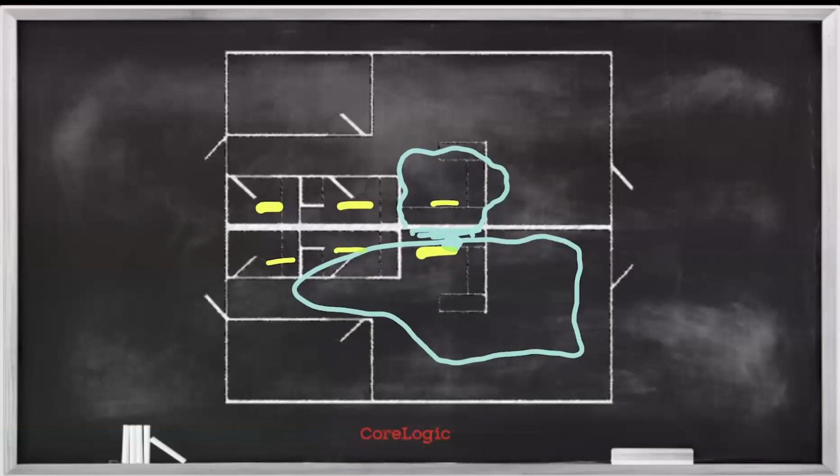The only reason this wouldn't be 2 entirely separate drying chambers is, let's assume that maybe that leak was a category 3. And if it were a category 3 and had affected this common wall in between the two, I'd probably demo that common wall, right? And as soon as I demo that common wall, I can create airflow and circulation between the two units, okay? Depending upon how that common wall is constructed and what materials it's comprised of. But most of those materials, especially if there's insulation present and we're dealing with drywall, that wall would have to come down. So apart from that scenario, these would be 2 entirely separate drying chambers.